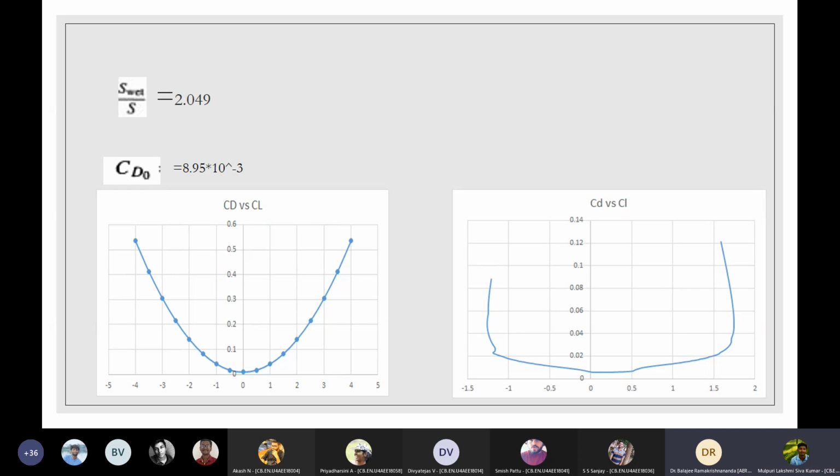Using the cruise CL you can find it. Don't find the angle of attack right now; you can do it later. Now, where are the curves comparing with 2D? CL versus alpha. Sir, you have shown two curves here, CD versus CL. What are those? Right hand side is 2D and left hand side is 3D. Similarly, compare CL versus alpha also.